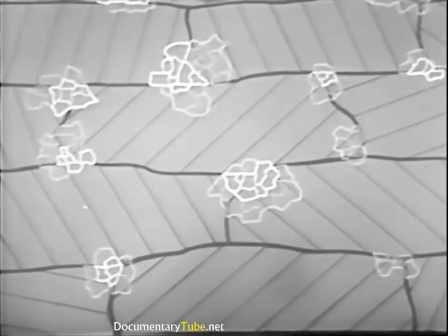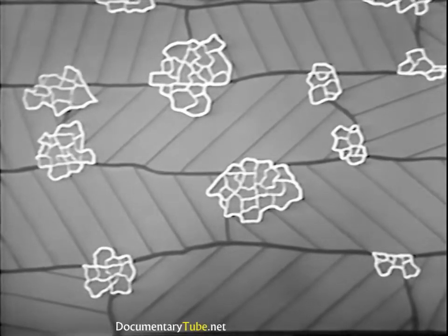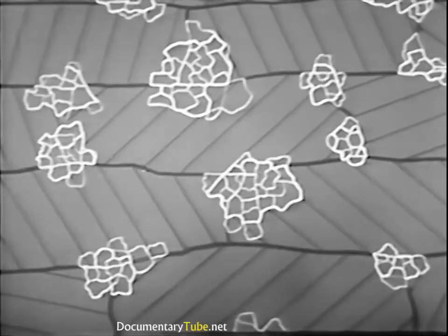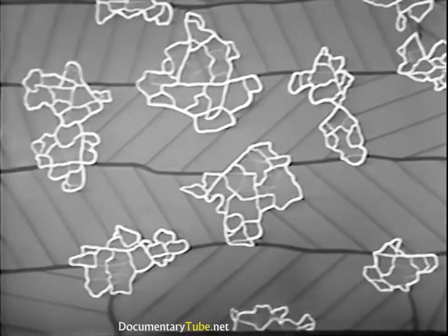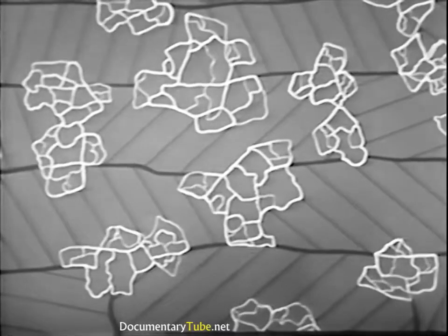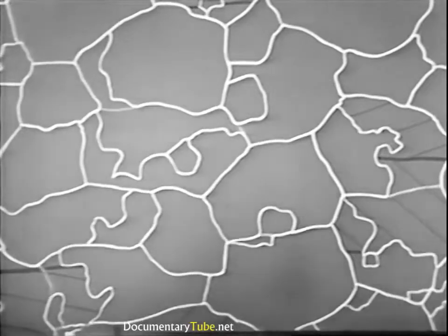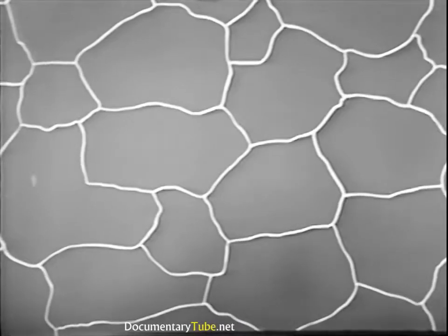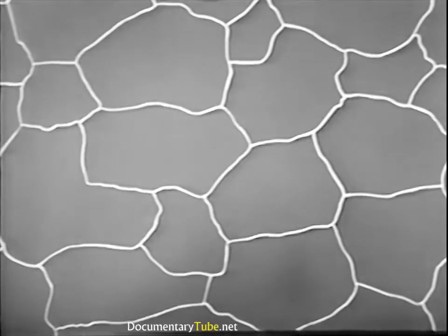When the temperature is raised to a point called the recrystallization temperature, nuclei of new grains are formed from the fragments and crushed particles of the original grains. As the metal is heated above the recrystallization temperature, but below the melting point, these stress-free crystal nuclei grow into new equiaxed grains by merging with the other nuclei and by accretion of material from the surrounding stressed metal. At elevated temperatures, the new grains may become quite large. The alloy is now in its annealed or soft condition.